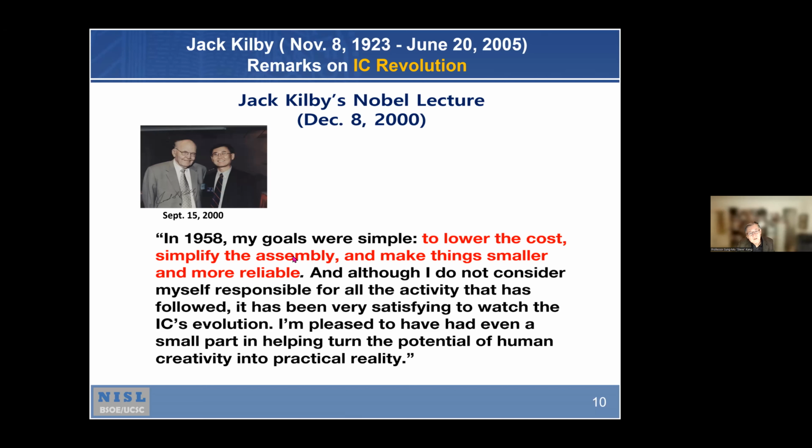In my opinion, the integrated circuit is like packaging in a sense. So that simplifies the assembly process. And then transistors are smaller, interconnections are shorter, and reliability is also achieved. Many reliability issues in electronics come from the contacts in interconnects.